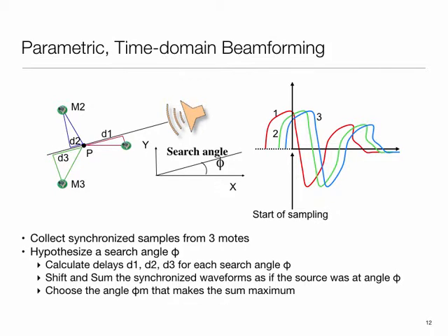One technique which is very commonly used is that we try to detect the direction from which a sound signal is coming. The idea is that some acoustic event happens, and if two nodes can figure out the direction, then we can do an intersection of the two beams to figure out the location. The way direction is figured out is the following: at each node we have multiple microphones. These microphones are all time synced, and they are in a somewhat distributed array, perhaps on the order of a few meters.